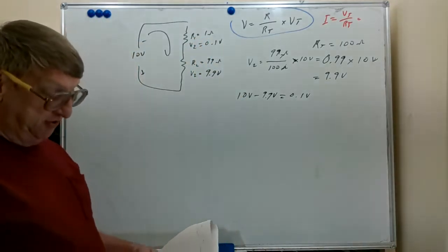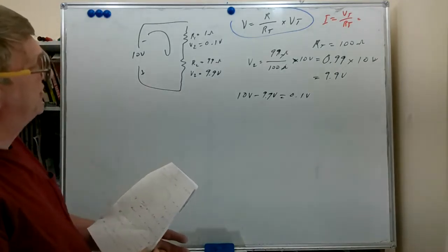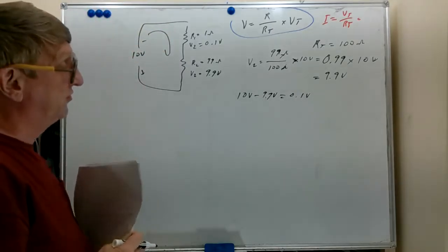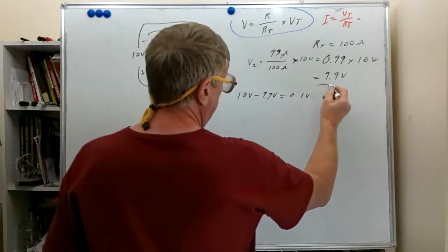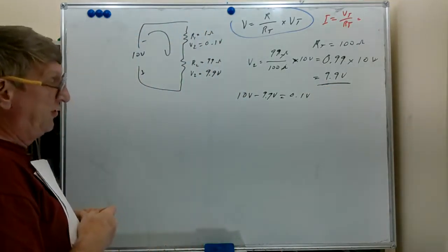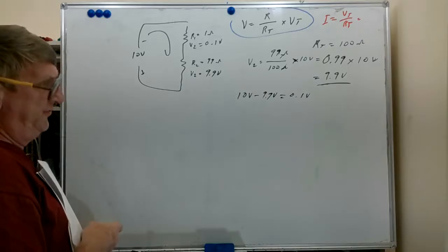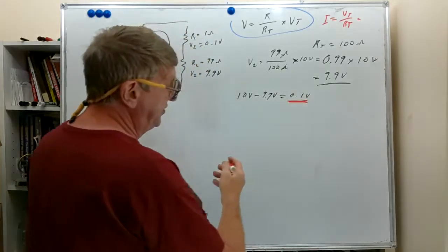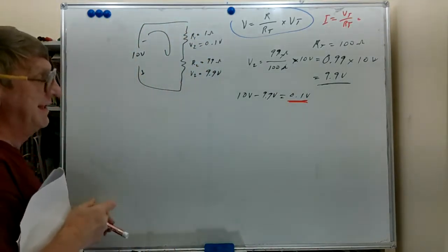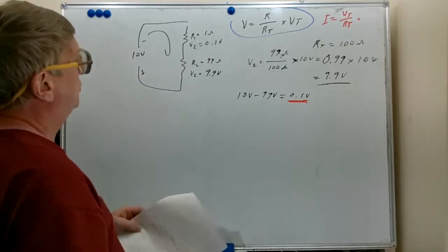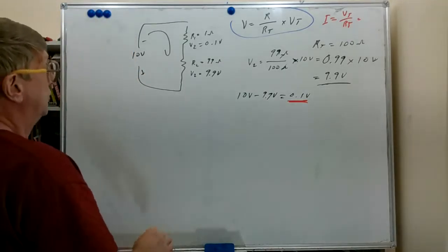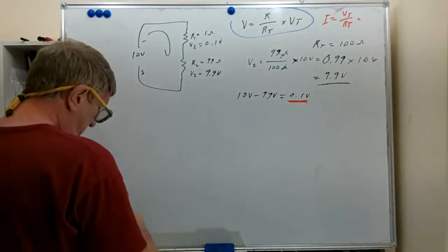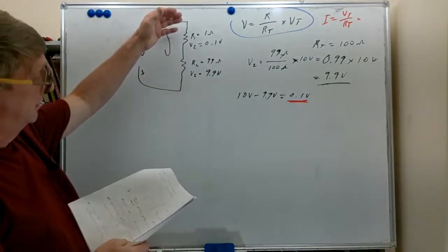We kind of did the same thing we just did in the last one, but here we have a big difference between the resistance of R2 and the resistance of R1. And you notice that almost all of the voltage appeared across the larger resistor, 9.9 volts. That is most of 10 volts. And almost none of the voltage, 0.1 volt, that is hardly anything, appeared across the smaller resistor. So when you have a voltage divider network, we utilize one with only two to demonstrate our claim here.